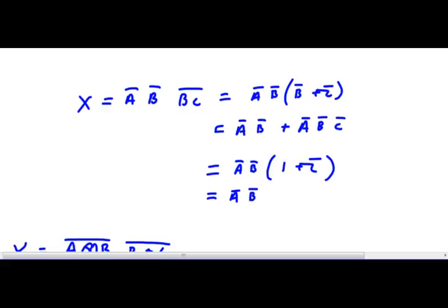Number 6. Why is it important to store MOS ICs in anti-static foam? So this is a 3-letter answer. E S D. Electrostatic discharge. So electrostatic discharge, something that you can't even feel because it's not high enough for your own body to feel it, is enough to destroy a CMOS chip.